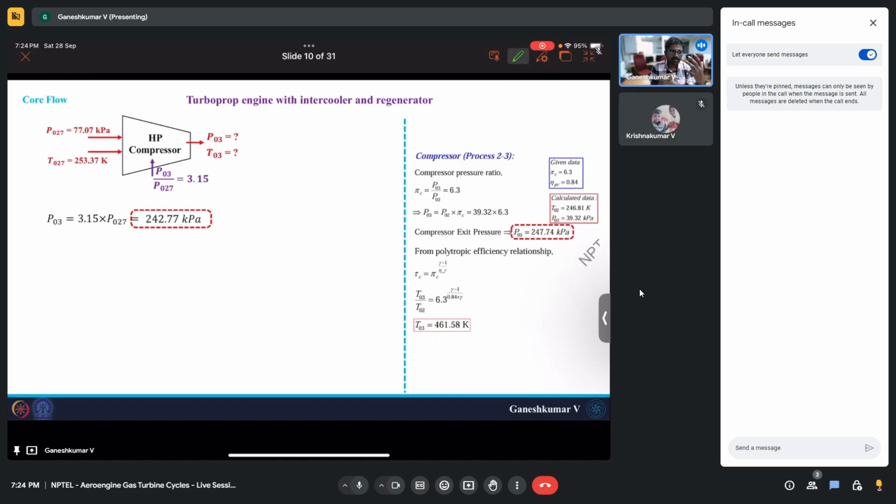And we can actually relate that because we have taken some heat out of the system, right? Which is nothing but some energy has been taken out, and because of that, the amount of pressure rise that you get in the compressor would be relatively small compared to what we got in the lectures when we have a single unit as a compressor. And similarly, you will also end up having a lower temperature because it is intercooled. It's straightforward. So if you substitute these numbers, you will end up having temperature to be 374.32 Kelvin, which is as expected because our air has been intercooled in between. So after compression, it has to stay at a lower pressure and temperature compared to the case where the intercooling hasn't happened.